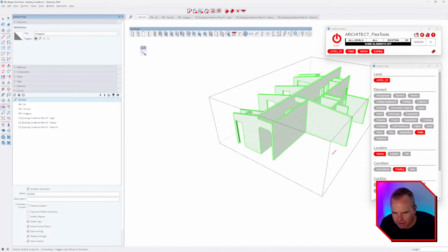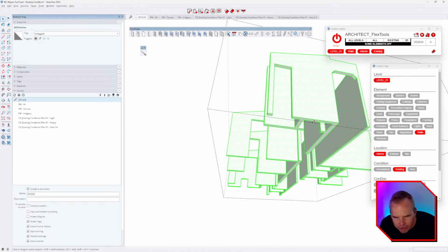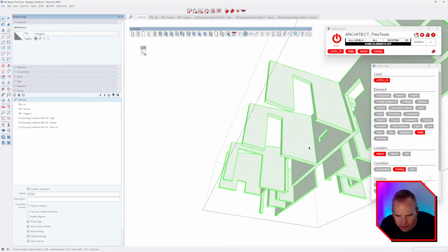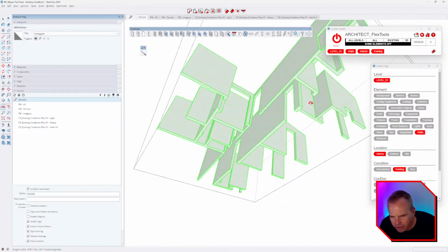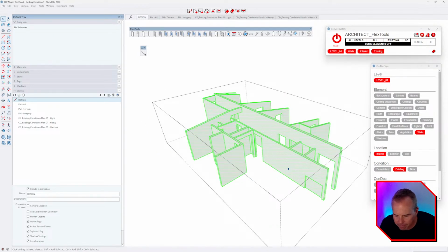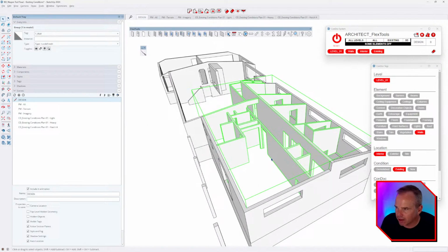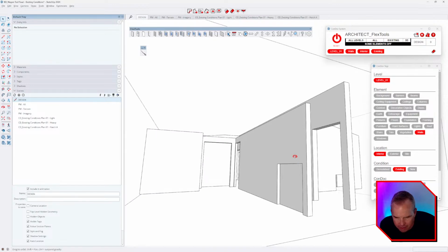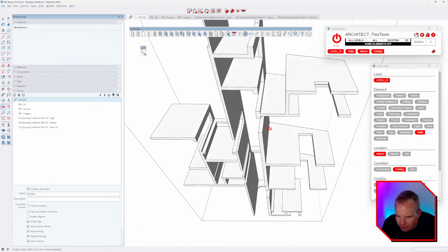And you can see we're missing a surface right there. Just give it our best once over to look for any missing faces or extra edges. I mean, looks decent. So now this is where the question is how far in do you want to go in making this a solid? You can see that in my entity info, it's just reading as a group. And what that means is that somewhere in here, there's just a little edge floating around.